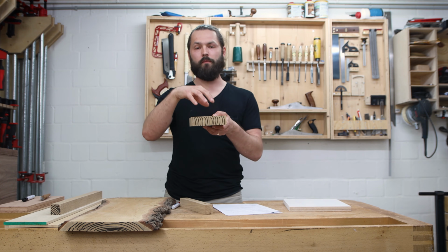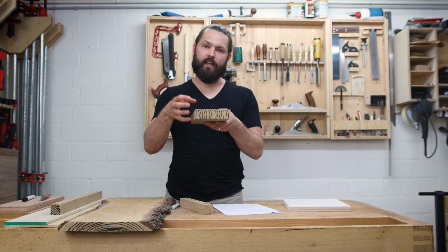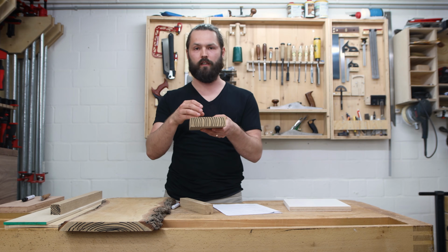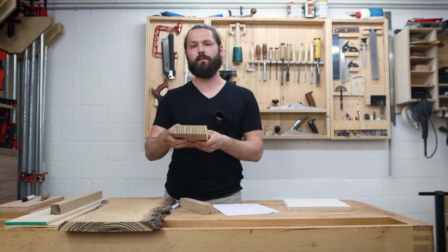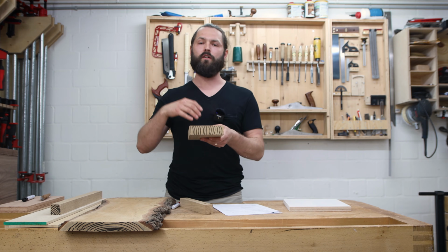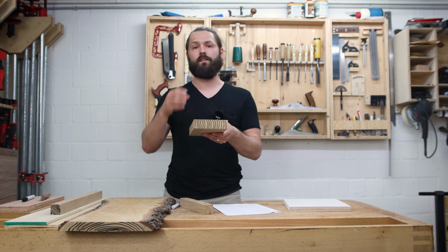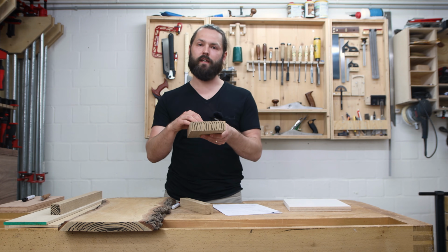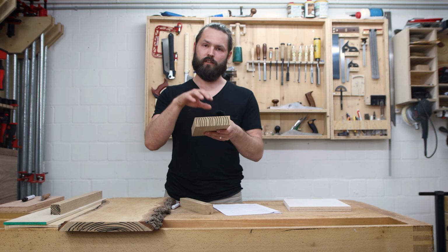Also keep in mind that when you put your lumber from outside to the inside, it strives for the equilibrium moisture content in the wood. So it will most likely dry a little bit more when it's here in your house until it has reached the equilibrium moisture content. That means that it's smart to put your wood inside your shop or inside your house for a few days, a few weeks, even a few months, depending on how wet the wood is when you buy it, to let it acclimate and reach that equilibrium moisture content level in your location.